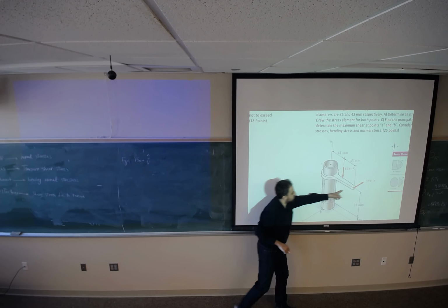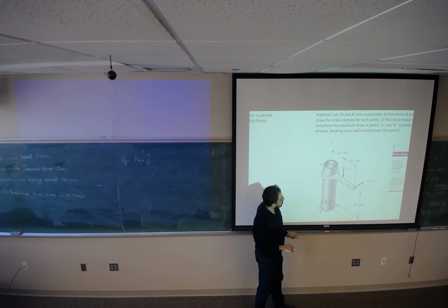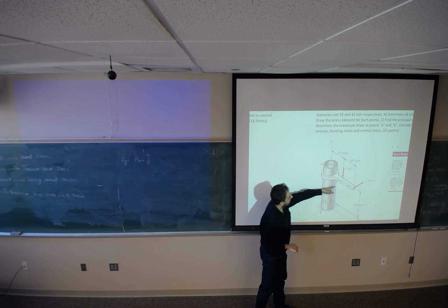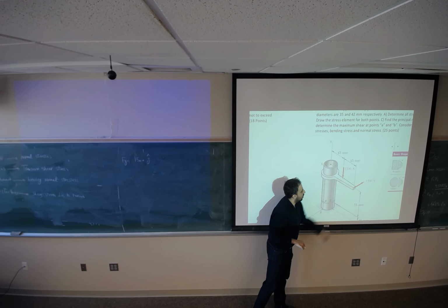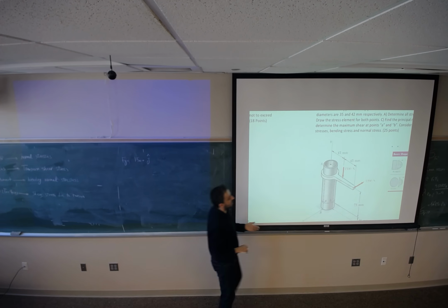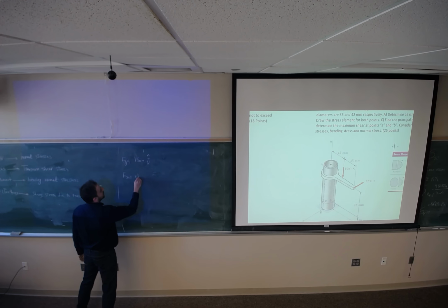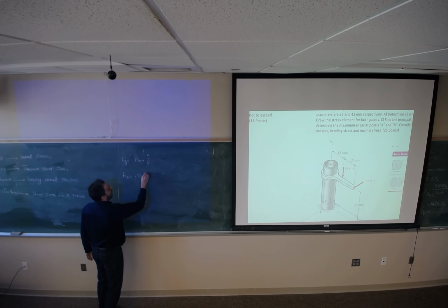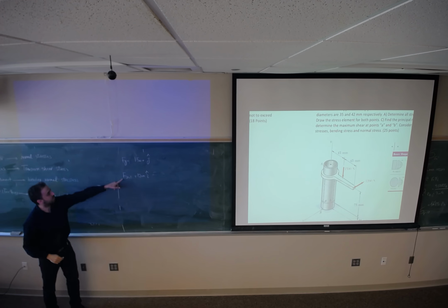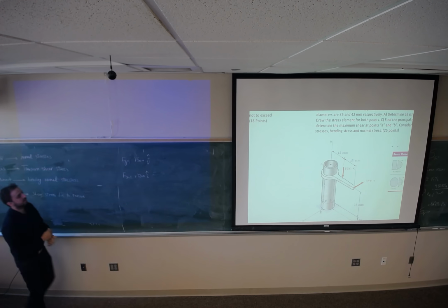This force is making 1200 Newton. Here at this cross section, we should apply the 1200 in the opposite direction, in x direction, positive 1200 i. So this makes transverse shear, and this makes normal stresses.